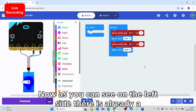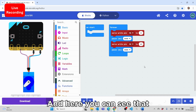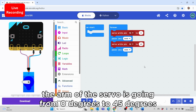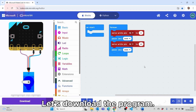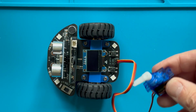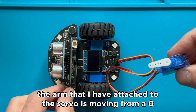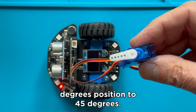Now, as you can see on the left side, there is already a virtualization of the program. And here you can see that the arm of the servo is going from 0 degrees to 45 degrees every 5 seconds. So let's download the program, and as you can see from the arm that I have attached to the servo, it is moving from a 0 degrees position to the 45 degrees.